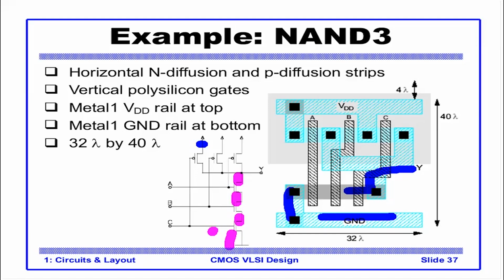and if you notice, the VDD should be connected to all 3 diffusions. But what about here? What about in the layout? Now in the layout, the connection from A to B, the connection from B to C actually, the PMOS, this particular PMOS and this particular PMOS, they are both flipped, in the sense they both share this common VDD. Why is this? Because we want to minimize contact, we want to minimize the metal length, metal routing. So this is one way of doing that, is that VDD is connected to A here, and this metal is being shared between B and C.